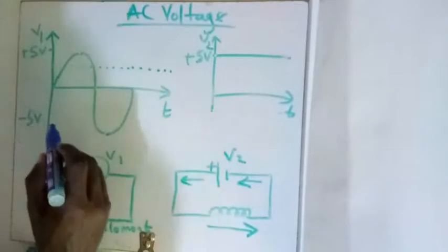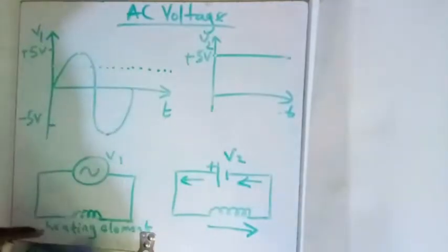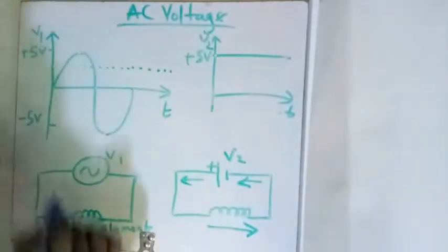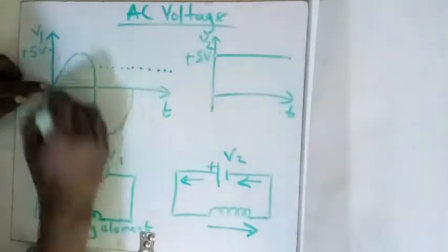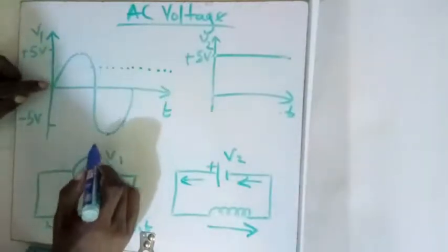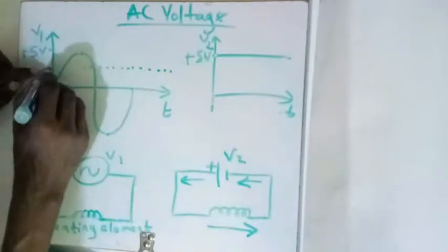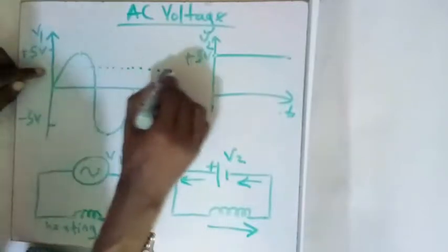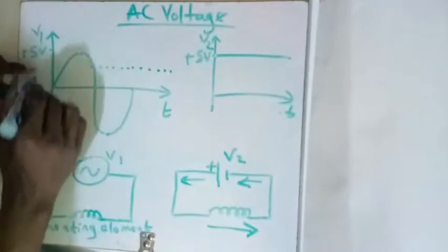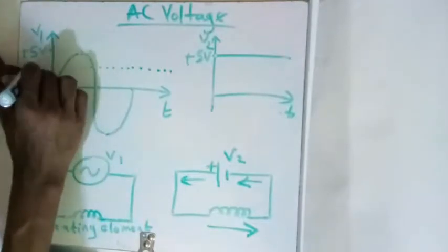The heat that you derive from this heating element in joules, when you apply a 5 volts peak AC, is like applying a DC voltage, a straight line, of a lesser value. You will get that same heat, and that is called VRMS.